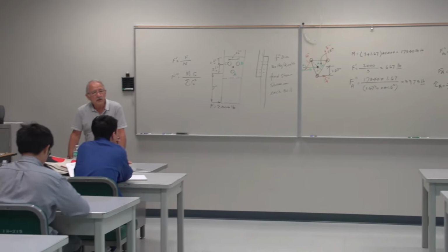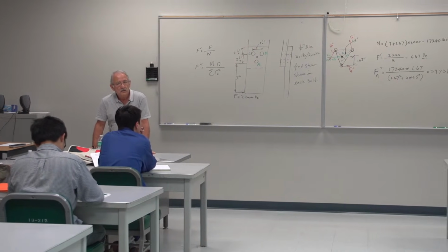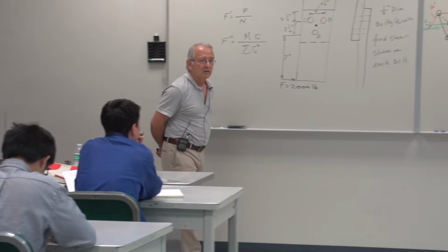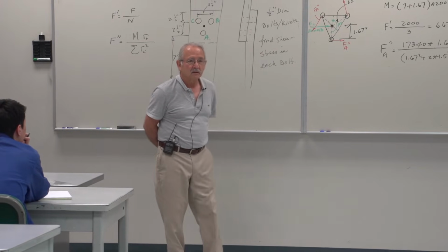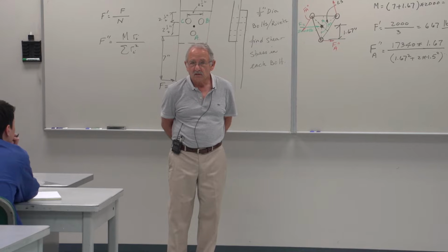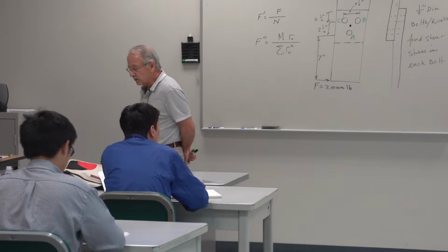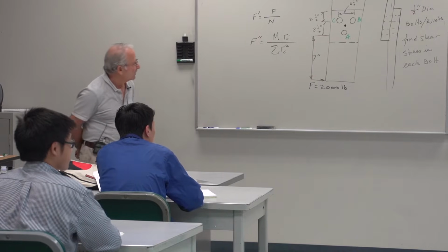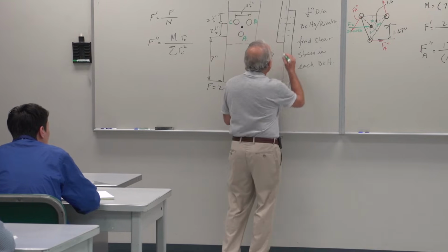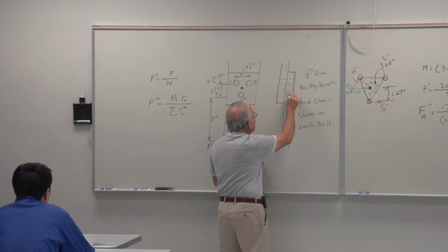How do you find the bearing stress? Let's say for A is equal to what? Remember bearing stress? I drew a sketch for you. It is equal to the load divided by this area, if we assume that these two plates have the same thickness.